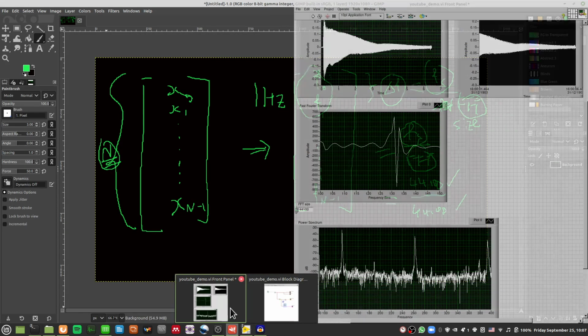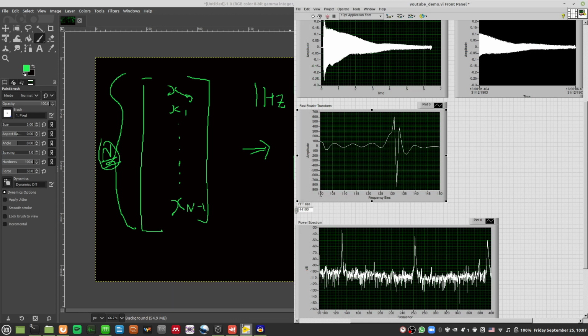So if I go to frequency bin 100, this corresponds to about 100 Hertz. The frequency bin at 130 corresponds to about 130 Hertz. If you do exactly like so, you will only take the first 44100 samples. But if your sampling rate is 44100 Hertz as well, then the spacing between each frequency bin will be 1 Hertz.